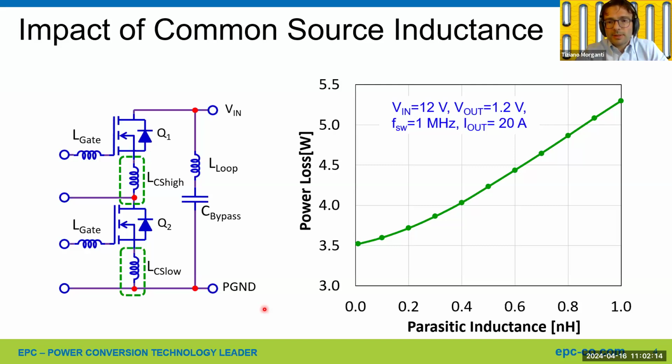One is somewhat increased capacitance in the switching node. It is not a big deal, maybe 10 or 20%. And the other drawback is when the Schottky diode is pushed hard, it still exhibits some sort of recovery. So it's not as perfect as, let's say, the integrated diode of our device, the freewheeling mode of our devices. But depending on the application, it might be used.